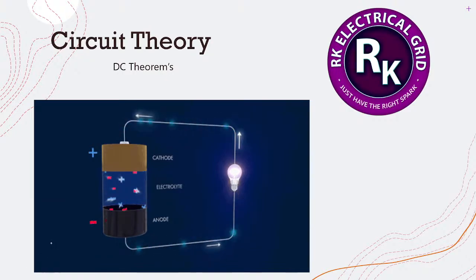So let us keep our attention. Let me bring some questions here. You should try to solve it by yourself, right? Now, as usual, let me take one dependent source and connect it with a resistor R. Here I'm connecting one dependent source, a voltage source, and its value is 2 times Vx, and the same voltage Vx is dropped here also.